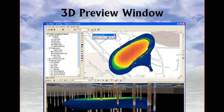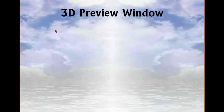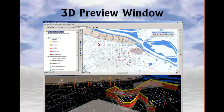Since a lot of people have Surfer around their office, I remember learning it in grad school, DOS version, and it's really great at doing contouring and gridding and the algorithms it offers, but it's not so GIS friendly. For instance, if you try to export the contours, there's no attribute value, so you can't color them basically. But we do little tricks to make it more GIS aware. We integrate with the 3D Analyst in ArcMAP, which we'll show you later. You don't have to go out into a whole separate application just to do 3D. You just toggle this 3D preview window within ArcMAP, and you can interact with the scene right within ArcMAP without having to go out to another program.